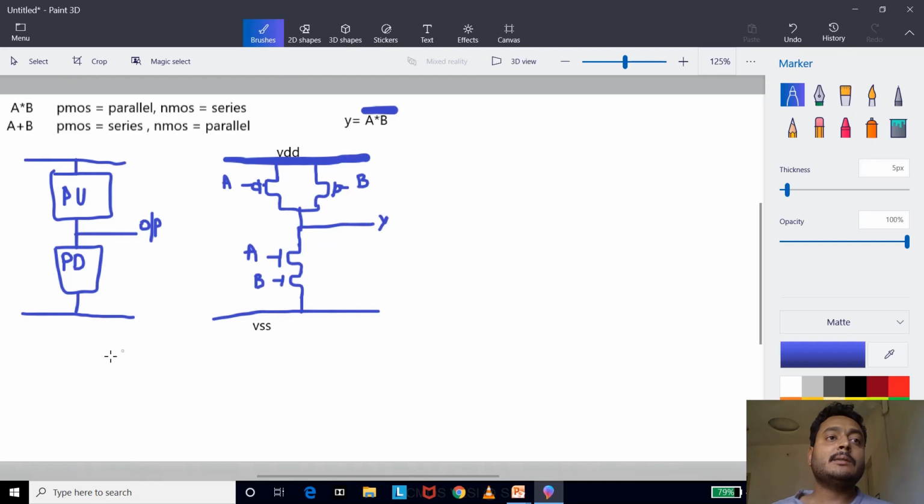So I will try to write the graph from this particular node VDD to Y. Okay, so this is my say VDD point, and this is my say Y point. Okay, say this is nothing but VDD. Okay, and this is nothing but my Y point, and I need to draw the graph how it goes. So from VDD to Y, this node to this node, the different paths available are, so from VDD I can go through A and I can reach Y. So I can write this from VDD through A I can reach Y.